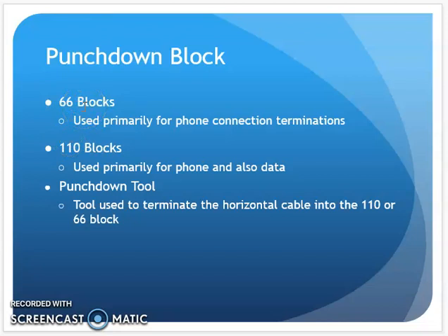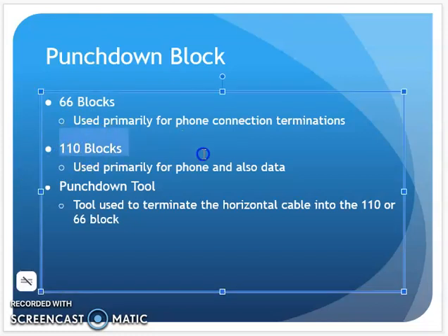I hate to use the word old school, but I'm putting little air quotes around older analog phones. 66 blocks got used to terminate that. Later on, 110 blocks got used for phone and also for some data. And the terminations to them got handled with a punchdown tool.